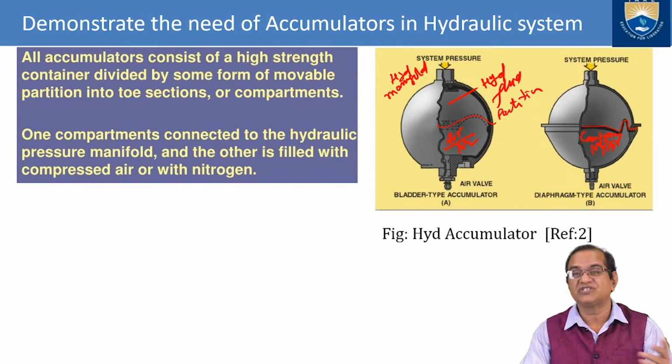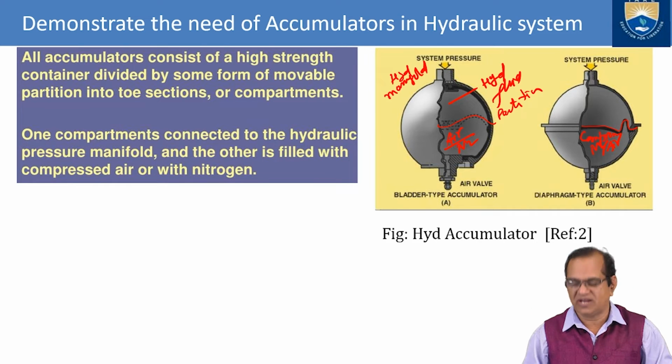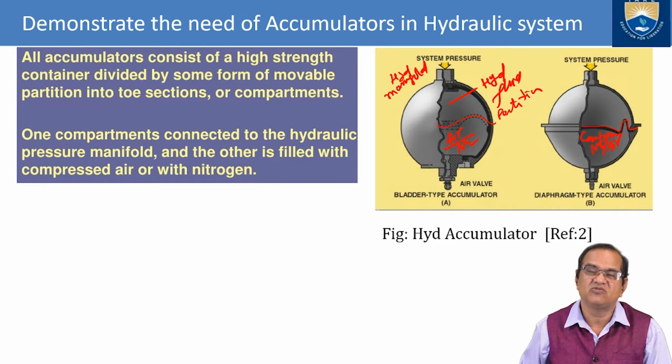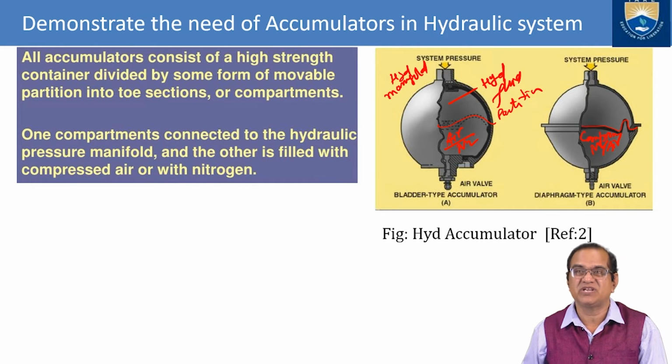So in this way it is functioning, and it serves as a safety and emergency measure. In case your hydraulic system also fails, for a few minutes your accumulators will work and give the power supply so that the aircraft can land. The emergency operation can be performed by the pilot.